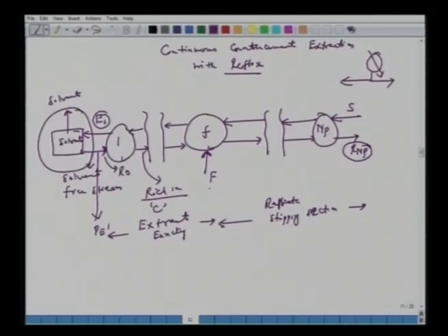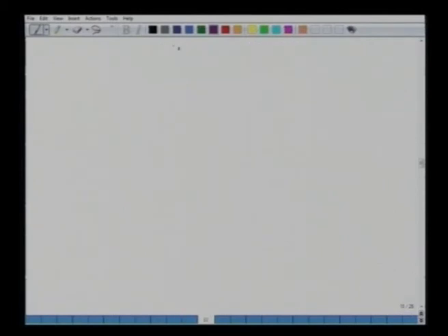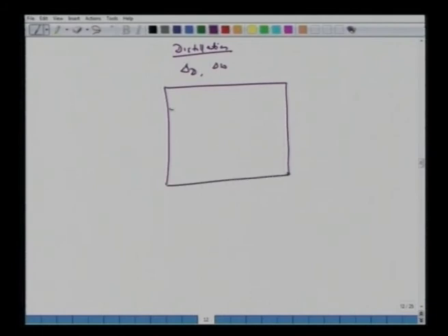Now, if you recall, in the case of the distillation column, we looked for two difference points, delta D and delta W. Essentially you have the Ponchon-Savarit method where you plotted HV and HL, and here you had X, Y, and then you looked for one reflux here as delta D, and at the bottom you had delta W. So just qualitatively, if you want to address this extraction with reflux, one follows a similar approach.